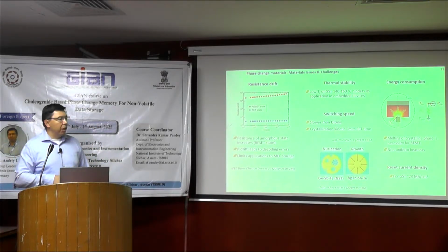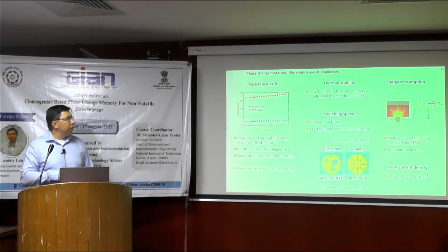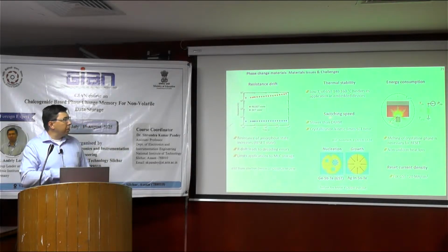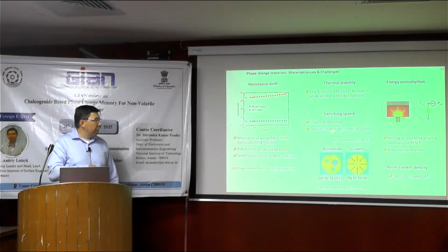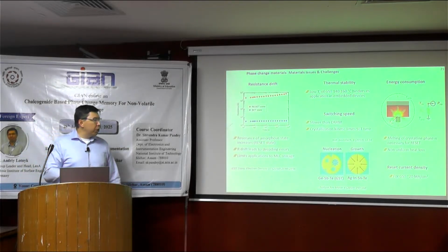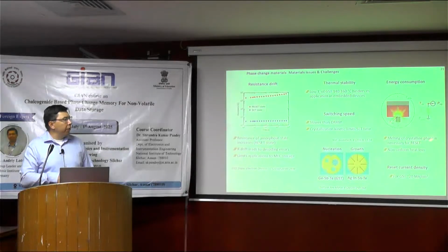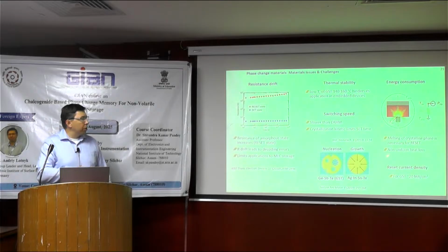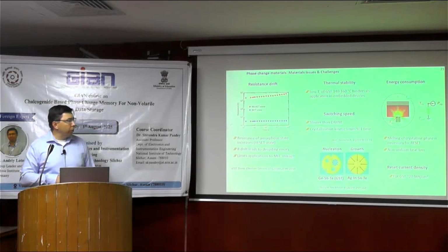Another problem is the thermal stability. The phase change materials crystallize at really low temperatures, like 140, 160 centigrade, and it hinders their application in embedded devices. It also has limited switching speed. It's still slower than DRAM, and crystallization kinetics limits the set time. And energy consumption. Also, one issue is that melting of the crystalline phase is necessary for reset, and non-uniform heat loss also contributes to this problem.